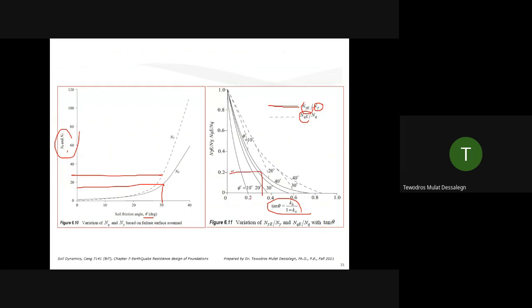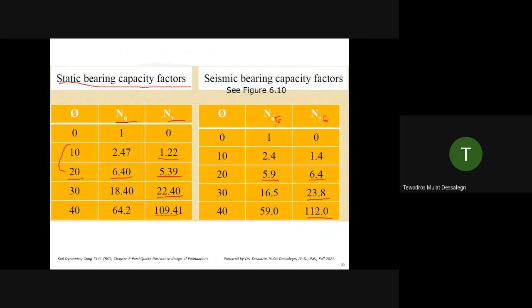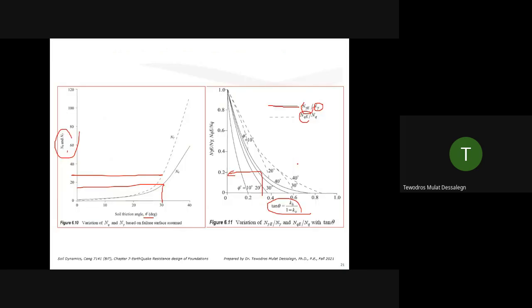So this is just the same relation as the table, but it gives you more complete information. If you have the data, you can use it, but if you don't have it, the figure would provide you everything. Especially if it changes from site to site depending on the acceleration values, this is better to use, because the seismic coefficients can vary.